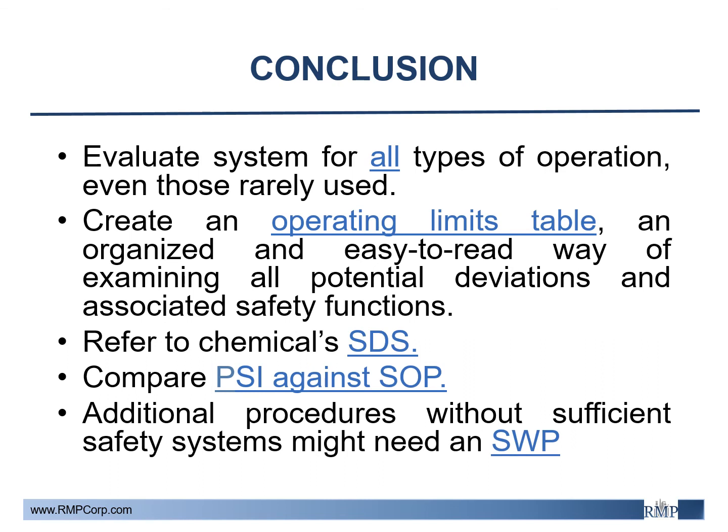In conclusion, the NDEP has provided very helpful guidance documentation for the creation of your facility's SOPs. It includes these major points to keep in mind. Evaluate your system for all types of operation, even those rarely used. Create an operating limits table, an organized and easy to read way of examining all potential deviations and associated safety functions. Refer to your chemical's SDS and compare PSI against your SOP. And lastly, additional procedures without sufficient safety systems might require the development of a safe work practice or SWP.